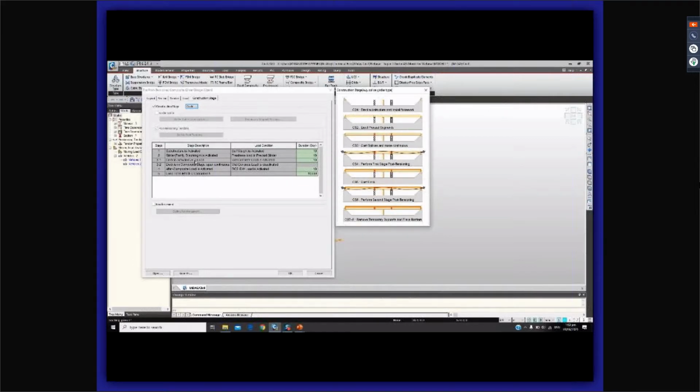And then for CS3-1, we have the deck being considered, and construction stage 3-2 is where the decks are considered as structural elements. And then for the fourth construction stage, after composite loads are activated already, like the wearing surfaces and the moving loads. And for the fifth construction stage, long-term effect is considered. So this is where time-dependent effect is acting onto our structure. So you can change the duration of each if you have tried it already.